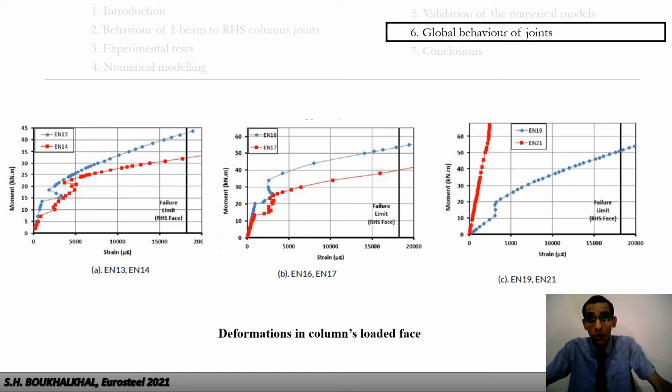This was due to the fact that the precision and symmetry of the stud rows, as well as the loading direction, play a significant role in the behavior of the joint, thus directly influencing the joint failure load.